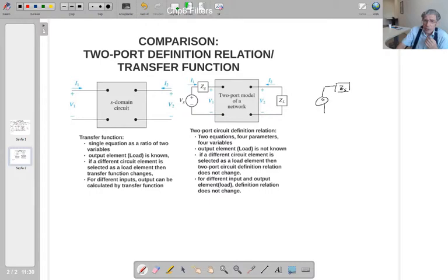ZS, VTH. We said there is a load here, Z load. We said this circuit, apart from the load here, in the original circuit, all the elements in here are replaced with that Thevenin equivalent, then we can find out this element's current and voltage. That was the Thevenin equivalent circuit usage in circuit analysis.